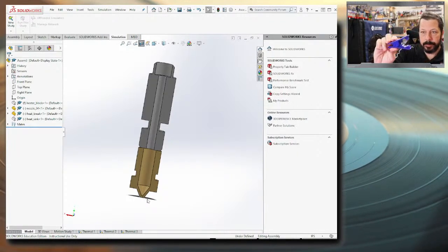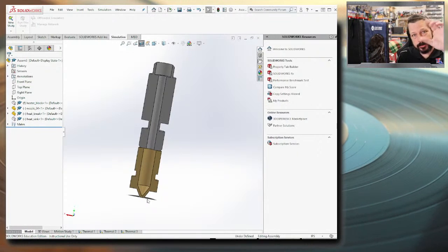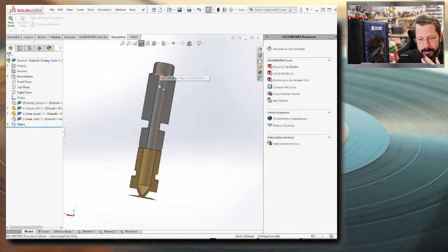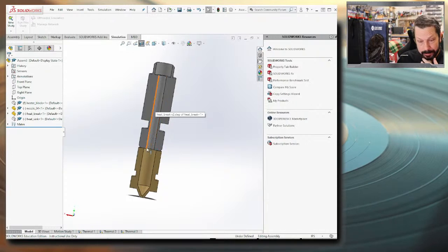You want a really sharp blade because you don't want to squish the Bowden tube, and you want it to be square because on a printer like that, and on this printer too, but this one I'll show you in a second why it's not as important, but it still is important. That larger area where the Bowden tube rests ends up way down here where the heat is still potentially hot enough to liquefy your filament.